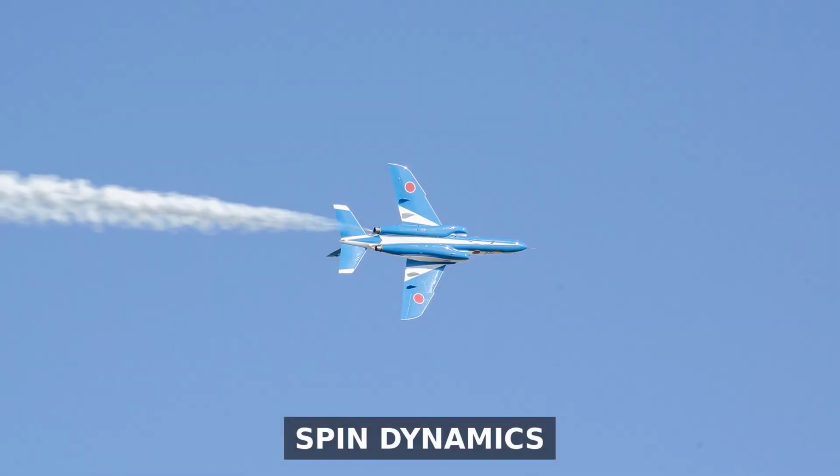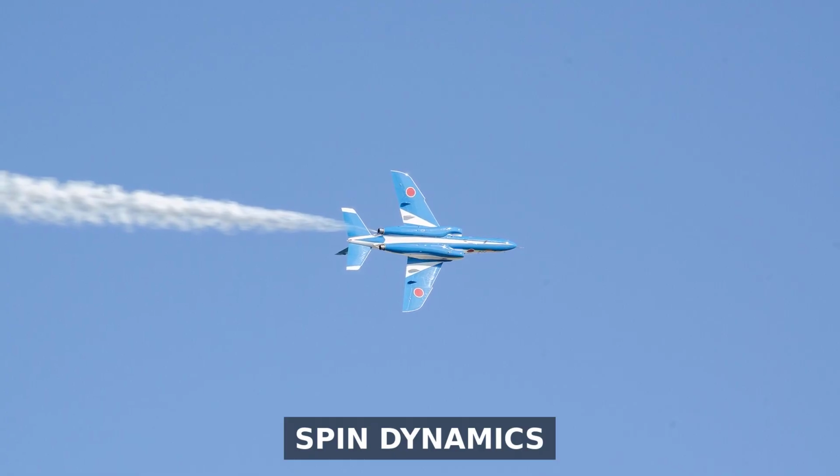In a fully developed spin, the aircraft rotates around a vertical axis while descending at a steep angle. Descent rates can exceed 5,000 feet per minute. At low altitude, a spin is almost always fatal. That's why prevention matters more than recovery.